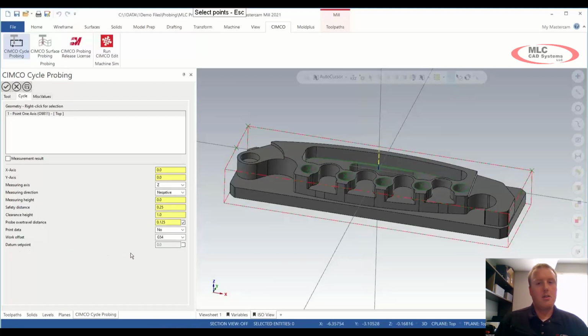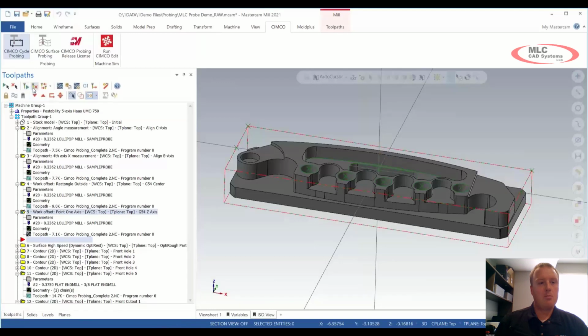point. What that's going to allow you to do is touch off on the top of the stock, but then say you wanted to account for maybe some material on top of that, and we want to actually drop it down an additional, say, minus 10 thou. That's going to go ahead and allow the probe cycle to then call that at 0, but it's also going to drop an additional 10 thou. That way, when you take, say, your face cut or something of that nature, everything is shifted downwards that appropriate amount. Again, we can compensate for that, of course.